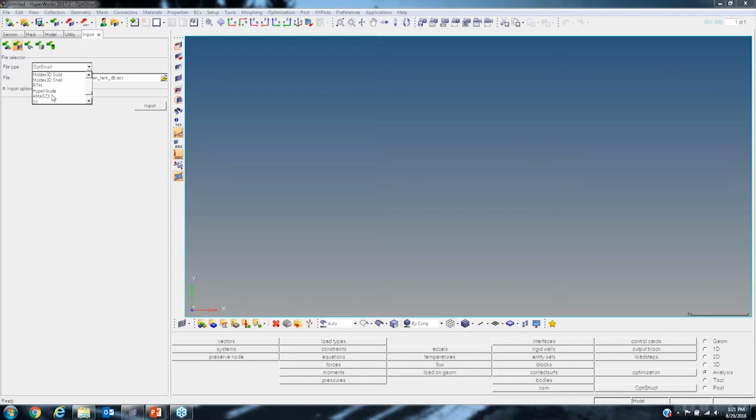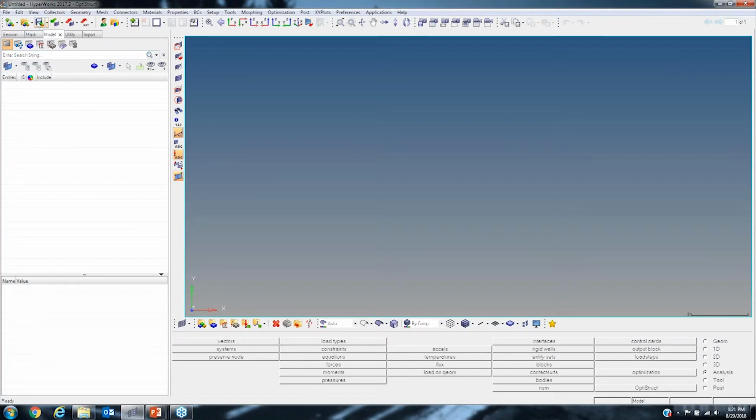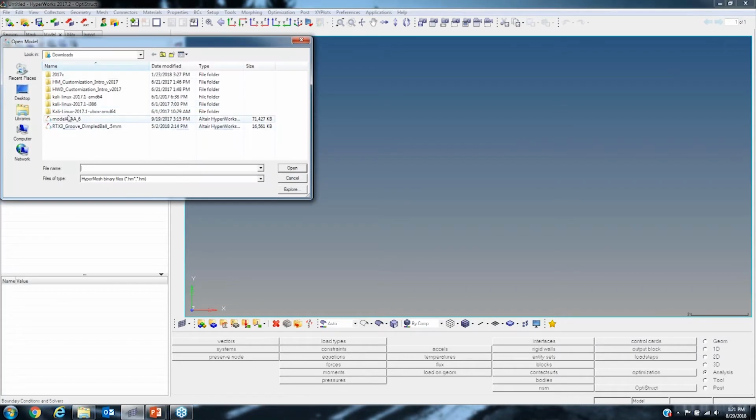What was the other one? We have pretty much anything really. Nastran, you can do Nastran. So normally, I know SolidWorks meshes in Nastran format, so when you export from SolidWorks, it'll be Nastran code. So you just bring in a Nastran code and import the mesh in here, and you'll be able to manipulate it in here.